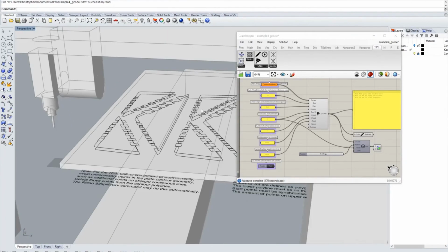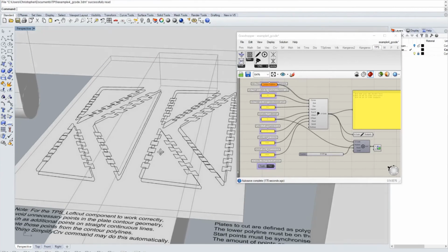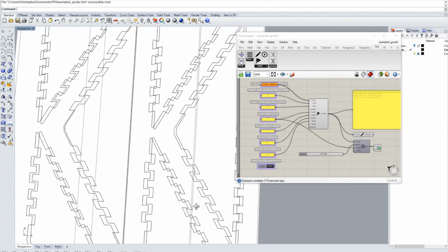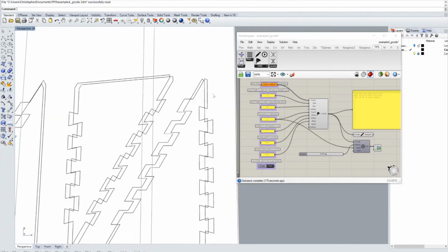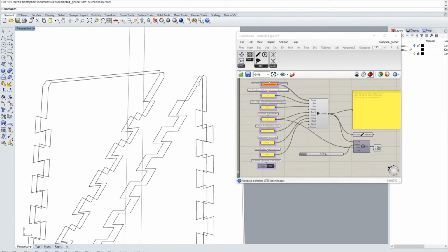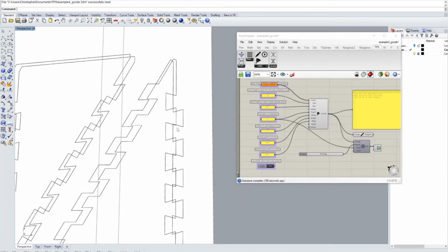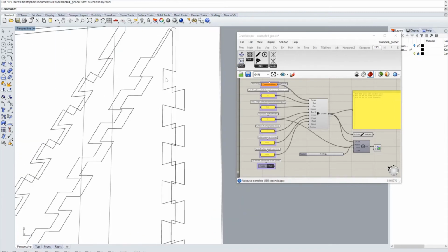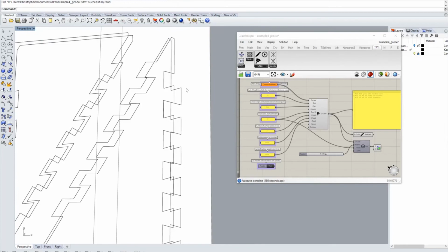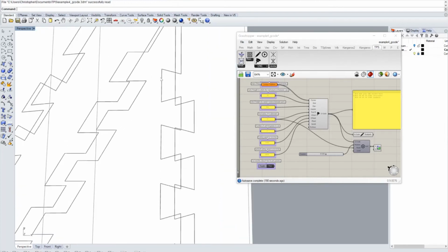So you see this is a lot more complicated plate geometry, which has these concave contours, which means out here at this corner we have a convex shape. But then once we get into these dovetails, there are concave corners. And with a cylindrical tool, which we typically have, we cannot really make these sharp corner cuts.